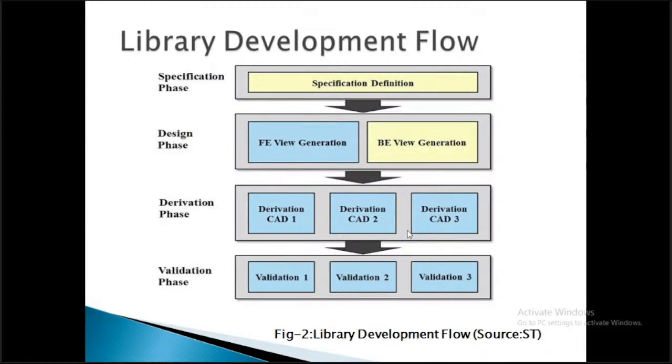It means the layout, GDS, schematic, Verilog model of each standard cell. And LEF, NDM, there are different kinds of data, Milky Way data we generate, and then finally we use it in our SoC, and then we have to validate each block first, and after integration we also validate our complete SoC in each case.